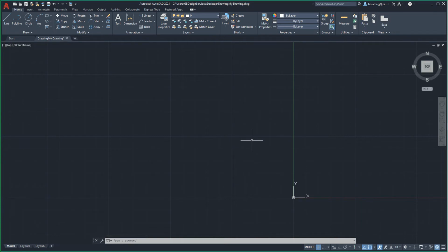Left-click one time on the Snap Mode icon to activate Snap Mode. The icon should be blue. Upon entering a drawing type command, we will use the line command for this exercise. Note that now your cursor moves about your workspace, yet it jumps or snaps vertically or horizontally in 1/2 inch steps or increments.